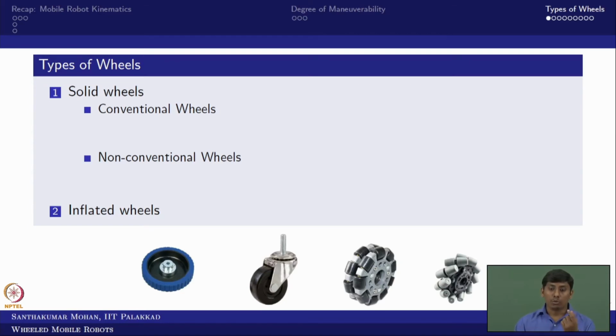Now if the roller is perpendicular to the wheel hub axis, then it is called an omnidirectional wheel. Whereas if the passive roller is inclined towards your wheel hub axis, as in this case where the passive roller is inclined, right? This is what we call a Mecanum wheel. We will talk about this in great detail. The fixed wheel means it is just rotated about that fixed axis, whereas steerable or rotatable means it would be rotating with respect to that axis, and on top of that, it would be steerable.